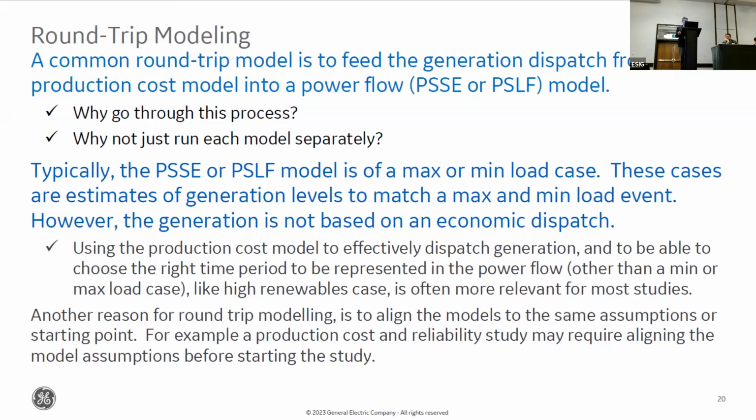So, high level, and I don't have the details that the previous presenters provided, we have done a number of round trips where we fed the dispatch generation from our MAPS model into either PSSE or PSLF. And as I explained before, the reason you really want to do this is you want to capture an economic dispatch of the power grid, and then use that in your power flow analysis.